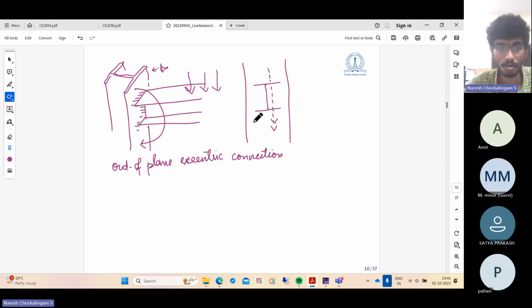In order to design it, you assume that the bending formula, the assumption of plane sections remaining plane, and the linear distribution of stresses holds. So we assume that the distribution of stresses in the weld group is linear. Which means the bending formula applies as well.